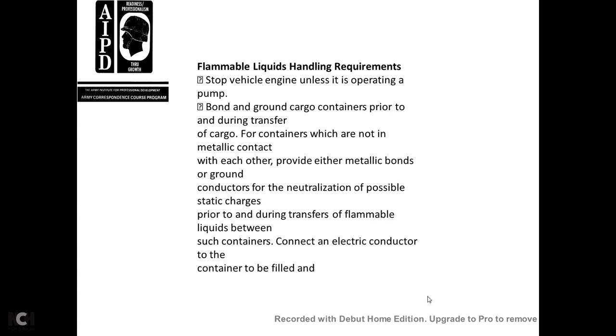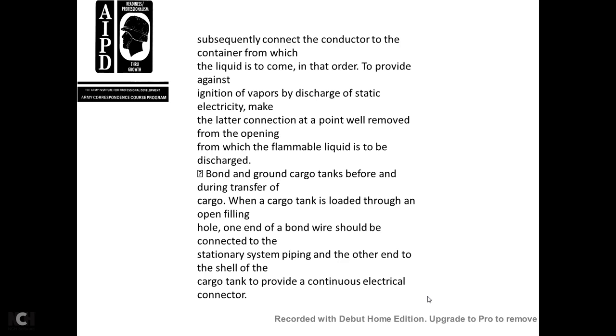Connecting an electrical conductor to the container to be filled, and subsequently connecting the conductor to the container from which the liquid has come, in order to provide against the ignition of vapors by a discharge of static electricity. Making a ladder connection at a point that will be removed from the opening where the flammable liquid is to be discharged. Bonding and grounding cargo tanks before, during, and after transfer of cargo.